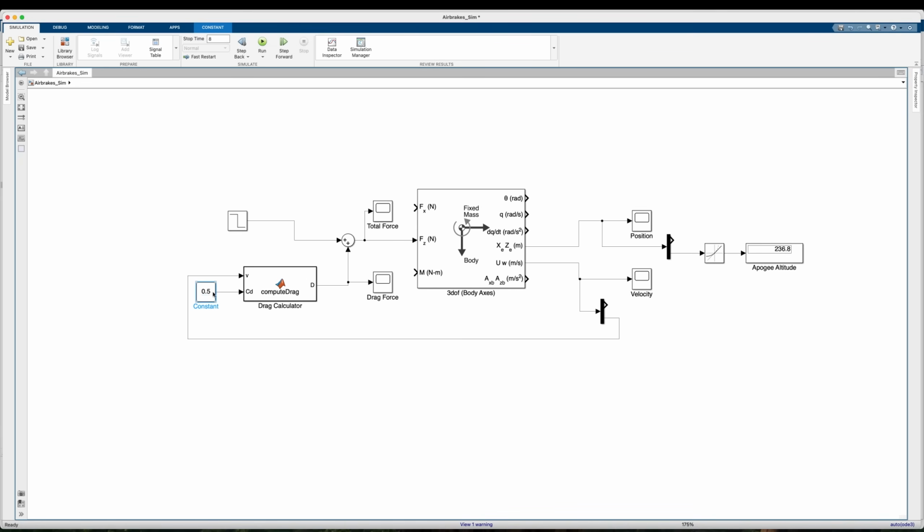The cool thing is this doesn't have to be constant. So what we're going to be doing is actively changing the drag coefficient with our guidance and control laws. There's going to be an intermediate step on our actual rocket where we'll have to turn a commanded drag coefficient into a commanded Airbrakes deflection angle. That's the thing we're actively controlling on the actual vehicle. But in terms of MATLAB, all we're going to do is our guidance and control laws will output a different drag coefficient.